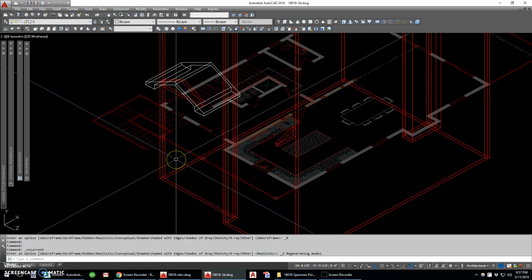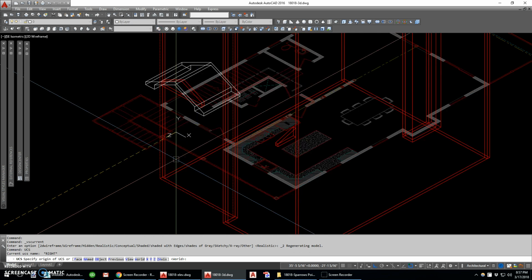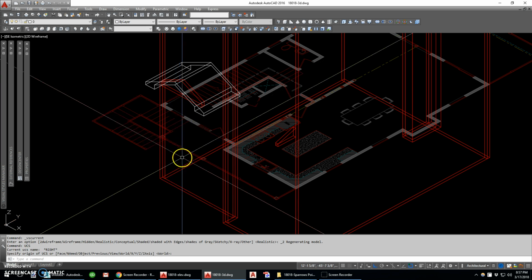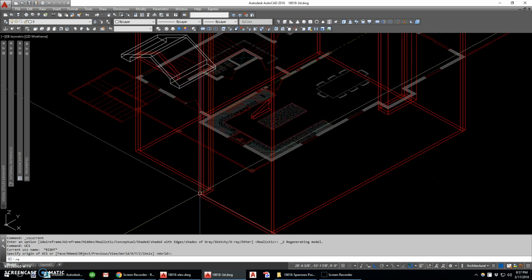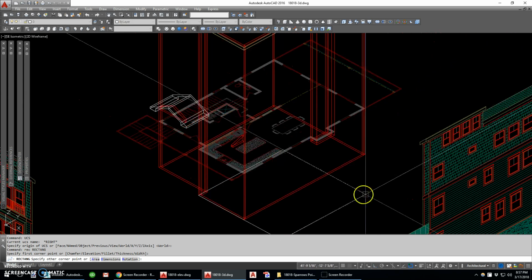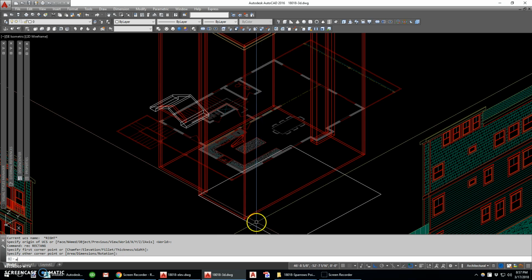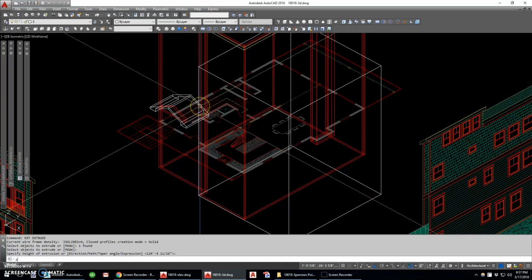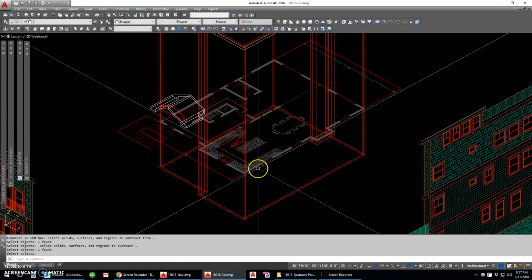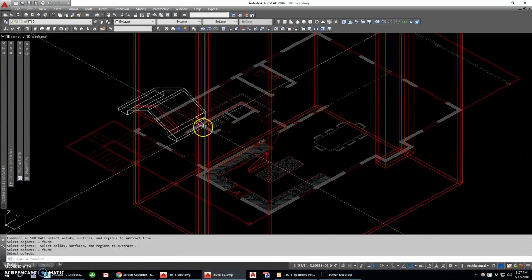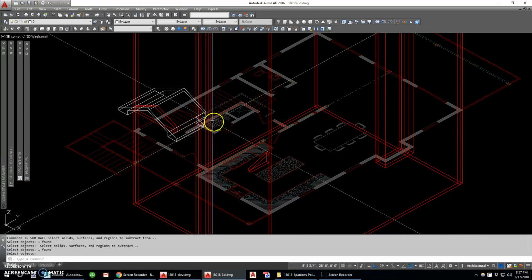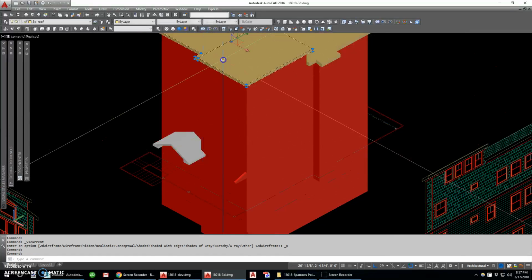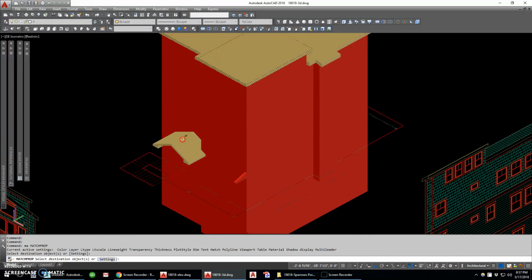So what I'm going to do is change my UCS back to flat earth, I call it, which is my ground plane, or my first floor level. And I'm going to draw a rectangle using this corner point just way far out away. I'm going to extrude that through that roof I just made and subtract it out of there. Again, you don't necessarily have to do that, but I like the geometry to be neat. It just makes things easier later. I'm going to go ahead and match the properties to our upper roof.